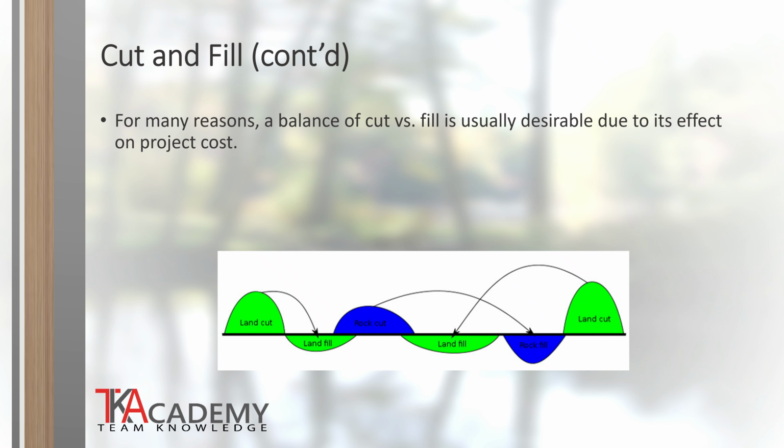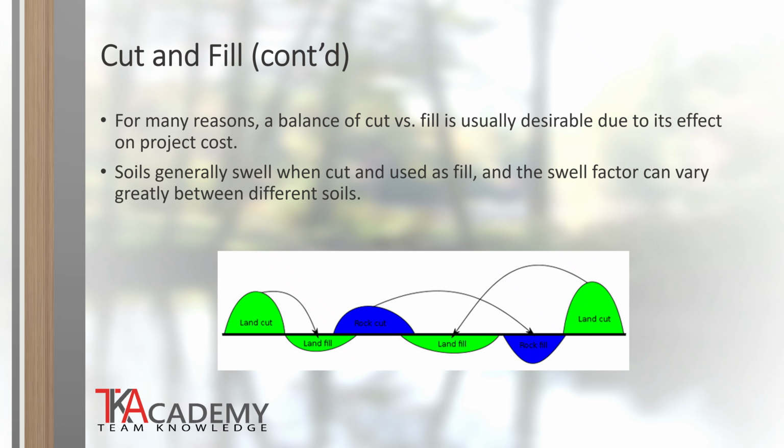A balanced site will neither require import or export of soil material, but will make use of the existing soil material on the site. Another condition to be aware of is the tendency for soils to swell when they are disturbed from their original position. This is usually caused by the introduction of air and water particles into the soil mix. The swell factor can vary greatly between different soil types.